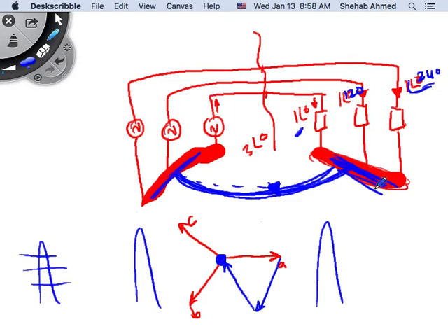If there's a voltage difference, or if there's current flowing, typically, in some cases, we will connect the ground with the neutral. We will talk more about that when we talk about protection here. If current flows, you know that there's a problem here. There's a big unbalance that you didn't design for. Right? So we have protection devices that look at that and protect against it. Okay? So the benefit of three-phase, we see it.